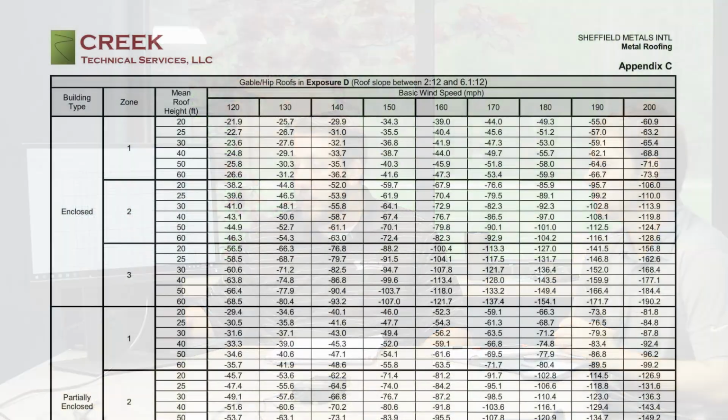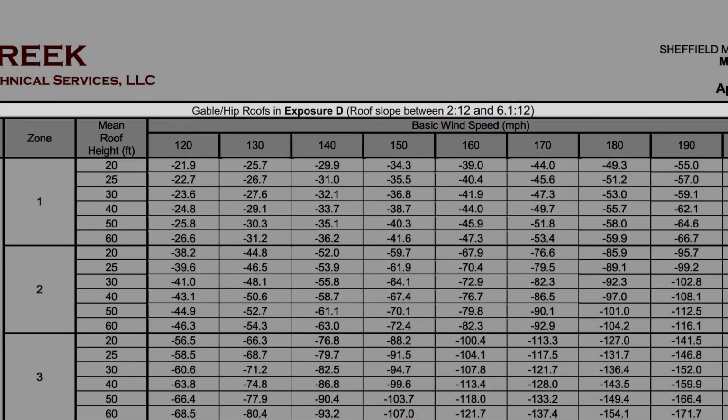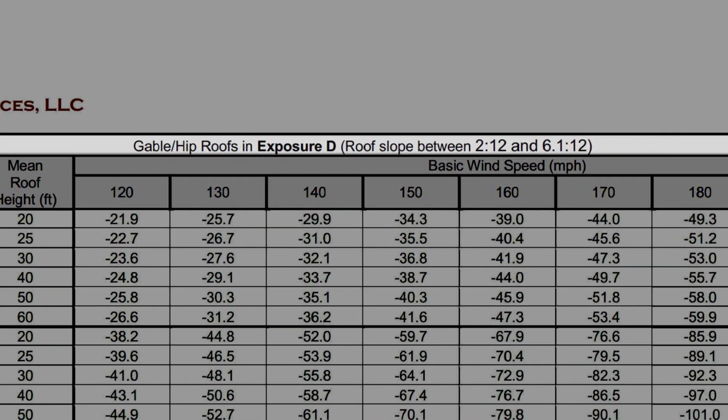That's the area that's really crowded and has a lot of obstruction, so a lot of wind can't get there. So let's look at the worst case scenario, and that's exposure D. All right, so exposure D, again, worst case scenario. These are the highest design pressures concerning the different exposure categories. These are where you're going to need to meet the most.